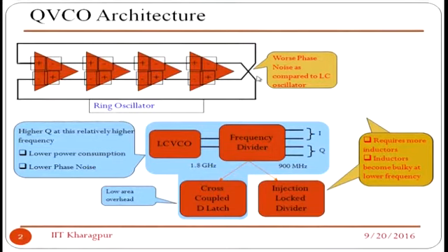It is basically a flip-flop, and then you have both the in-phase and the quad-phase components, and that divider divides by 2. That will give you 900 megahertz. That 900 megahertz is your GSM RF in. And also you have the injection lock-in divider, because which kind of divider you will be using will come later on. You can have current injection to that for better performance and so on.